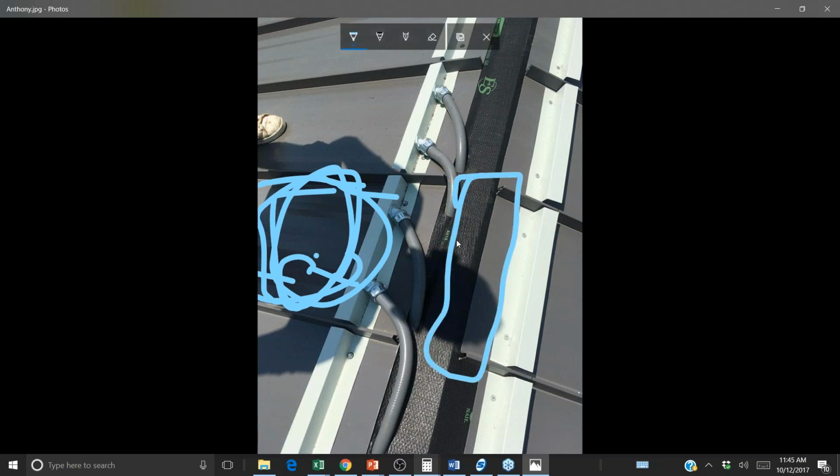But to make this array rapid shutdown compliant, we would either locate a rapid shutdown box on this side right before going in, and it wouldn't be a combiner box. We just take our circuits coming in, put them into a box, and have it be a rapid shutdown box. Or you could locate within 1 foot of the array, which is the hard part. You could locate the rapid shutdown combiner box right underneath the roof deck inside the building, where these cables are going into the building. But what you can see here is that we have 4 charge controllers.